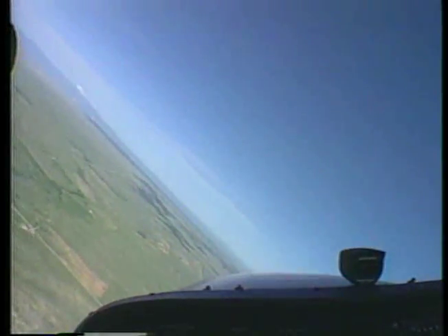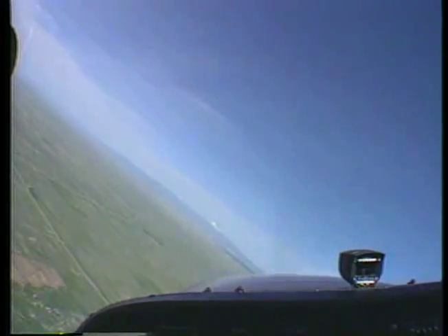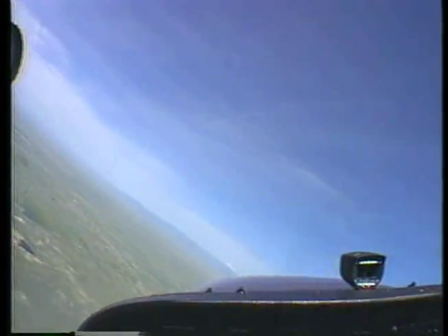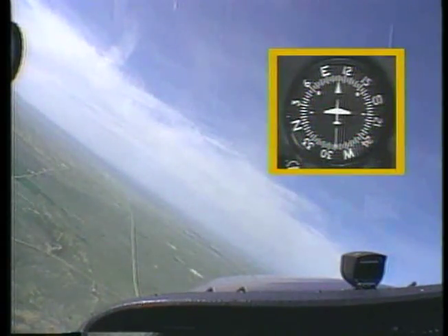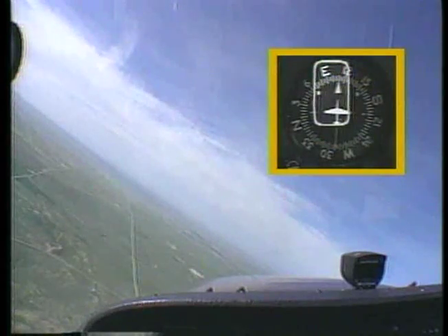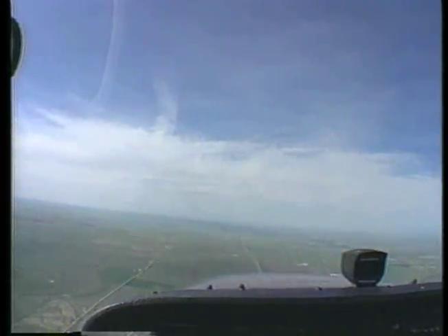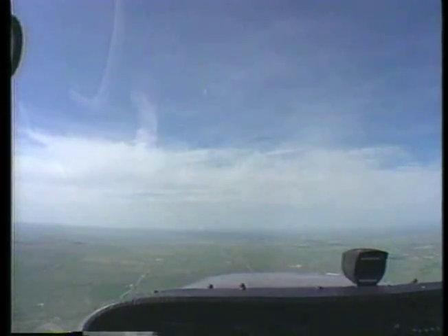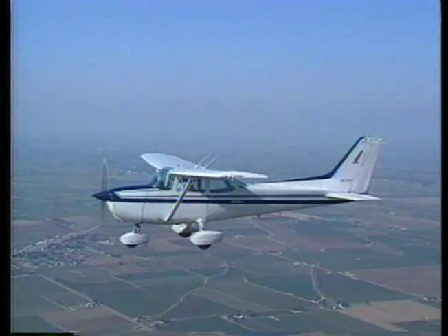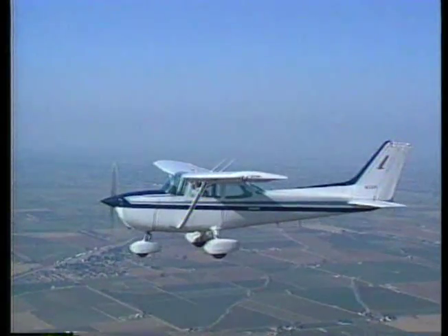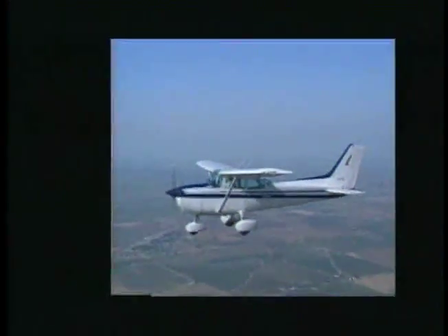If you're losing altitude and the pitch attitude is low, decrease the angle of bank slightly, then bring the pitch attitude back up to level flight and return to the desired bank angle. When you roll out of a steep turn to a designated heading or to your reference point, use the same procedures as for shallower banks, but initiate the rollout approximately 20 degrees before reaching the desired heading. As the bank decreases, reduce back pressure to maintain altitude and adjust the power to return to cruise. If you use trim during the turn, the last step is to relieve control pressures by re-trimming the airplane.